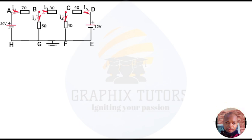So the first thing you do is consider each node, because nodal analysis makes use of KCL, the Kirchhoff current law, which says that the algebraic sum of currents entering or leaving a node is equal to zero. To save time, I will consider node B. I'll put my equal sign here, so the left hand side will be the current coming in and the right hand side will be the current going out. It can be any way. We are focusing on node B.